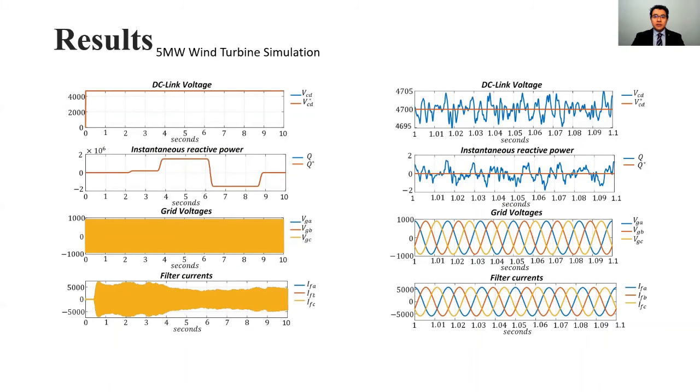This other graph depicts the behavior of the grid-side converter. We can observe that the DC-link voltage is close to its desired value. The reactive power follows the trajectory demanded, representing a supply or a demand of reactive power from the electrical grid.